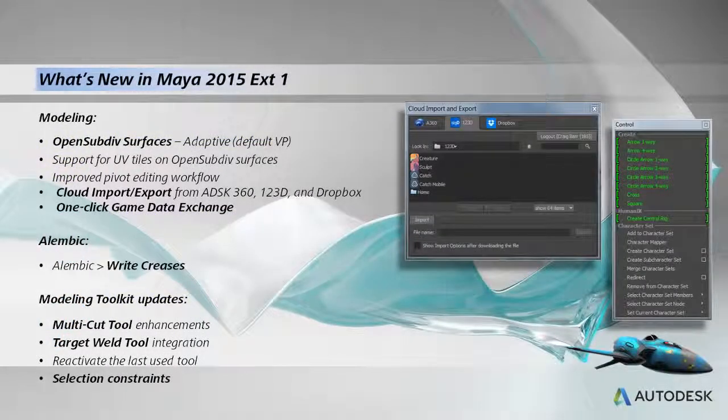So let's take a really quick look at what's new in Maya 2015 Extension 1. Now, I'm not covering everything here. There are over 37 enhancements available to Maya 2015 in the Extension 1 release. But specifically here, I'm highlighting some of the key points that have to do with modeling. So within our OpenSubdiv surfaces, we've added adaptive, and that will actually work in the default viewport as well. Support for UV tiles for OpenSubdiv surfaces, which is nice.